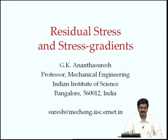We discussed in the last lecture what is meant by stress, and now there is a new term called stress gradient. Gradient usually refers to how a certain quantity varies with respect to a spatial dimension. The spatial dimension can be a thickness, width, length, some other quantity. In the spatial coordinates, if you take x, y, z as your coordinate system, how a certain quantity varies with x, y and z, that is called the gradient. That is a derivative of that quantity with respect to that direction, in one direction how that quantity varies.